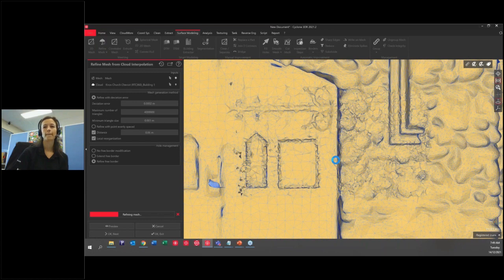Yeah, and if there wasn't any georeferencing information, you could also estimate those parameters, couldn't you, by picking some points in the point cloud? If you took a picture with your camera, or had a picture that didn't have any of that information, what you could do is use the dual screen in 3DR, where you have the picture on the left and your mesh on the right, and you can pick common points between the picture and the mesh, and that way 3DR will compute how the picture is oriented and positioned.